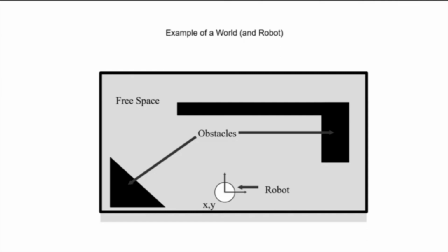So we have an obstacle and we have a mobile robot, which is a circular robot. Now the obstacle is marked in black, and we want to convert this into the configuration space. So what do I do? I shrink my robot by r. It becomes a point, and I increase this obstacle by the corresponding amount, that is by r.